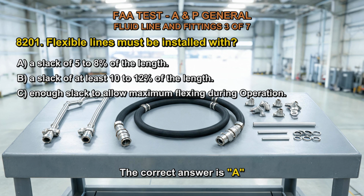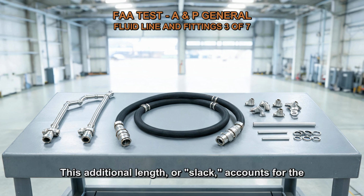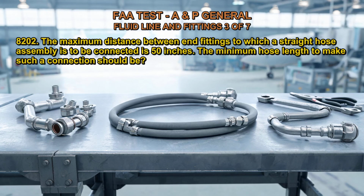The correct answer is A. Flexible lines should be between 5% and 8% longer than the distance between fittings when placed in a fluid power system. This additional length, or slack, accounts for the system's expansion owing to heat as well as the fact that a hose shrinks in length under pressure.